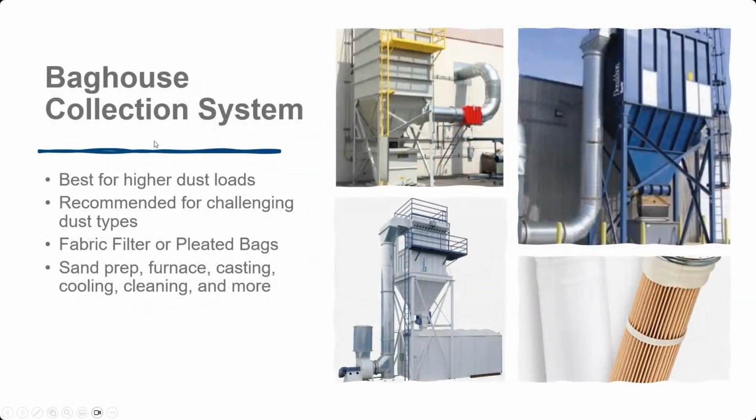And then the other type of collector is the baghouse or pulse jet dust collector. The pulse jet dust collector cleans during operation, and that was the main reason it was invented, I think back in the 50s or 60s maybe. Before that, they used shaker style dust collectors where they would have to shut off the operation and shake the dust off the filters.